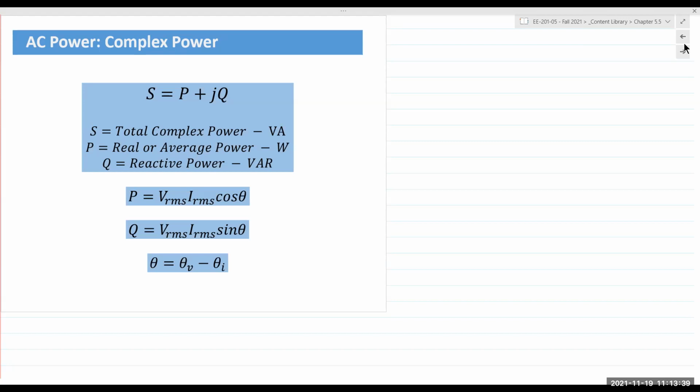So the reactive power, again, even though it's not doing any real work, is traveling back and forth across the transmission lines. When you send electrical power over long distance transmission lines, power loss occurs. We want to keep that power loss as small as possible. And that's basically what you're going to study here: how to analyze a circuit, how to find the power associated with the resistor, inductor, and capacitor, and also find the total power associated with the source or in the circuit.